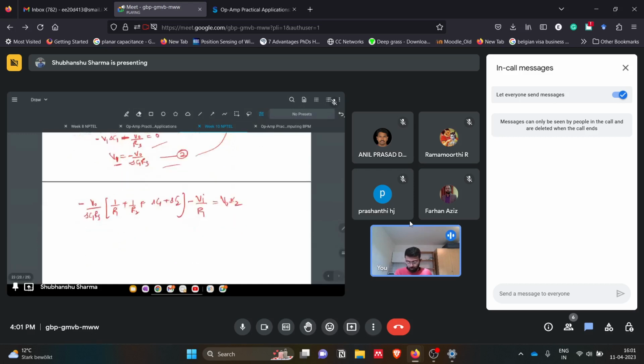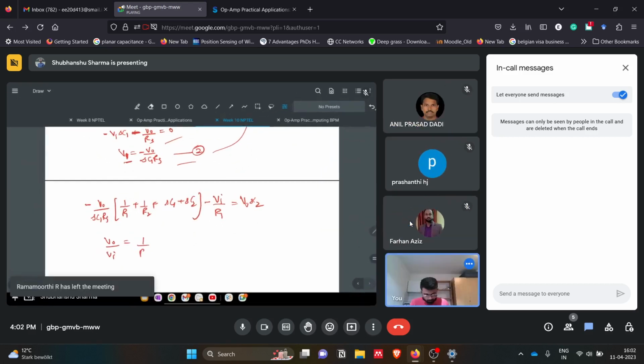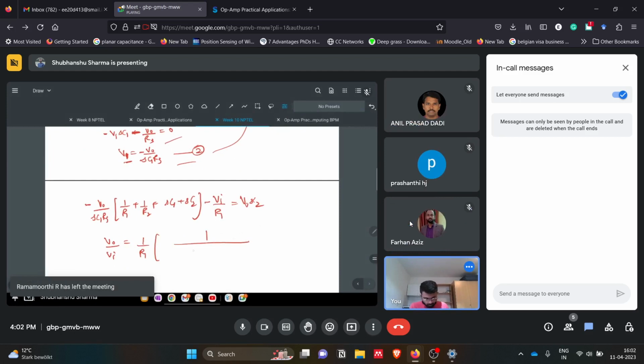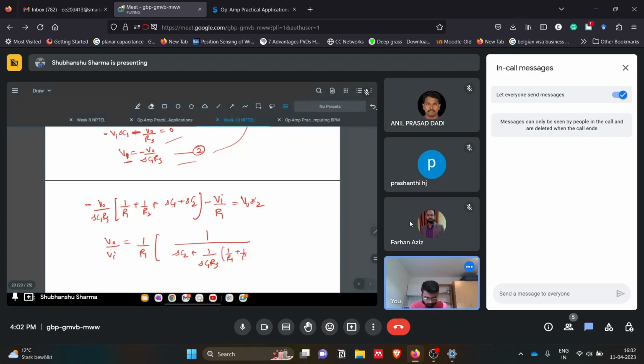Then V0 by Vi will be a little bit 1 by R1 SC2 plus 1 by SC1 R3, over 1 by R1 plus 1 by R2 plus SC1 plus SC2.